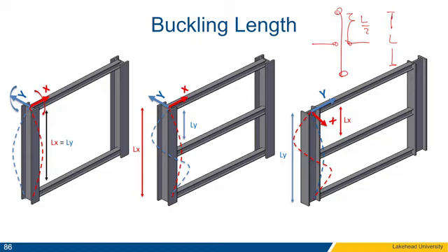However, it is worth mentioning what will be the case if you have unequal lengths of the column in between the constraining beams. So let's say the beams are located over here, so we have, let's say, a distance of 2 meters here and 4 meters here. In that case, both will be buckling lengths, but obviously the bottom one will be the governing one because it is the larger buckling length, and this may cause the failure in the column. And if that column were to deform, it will just deform in that shape.